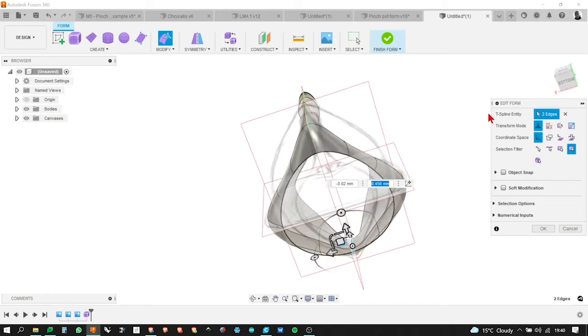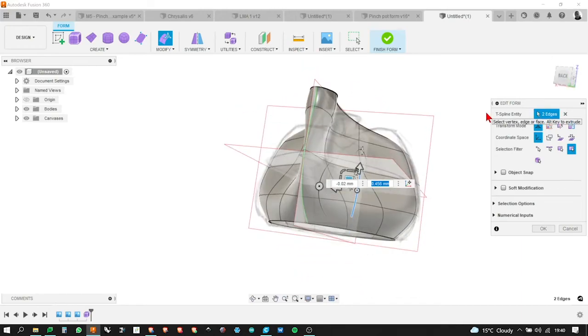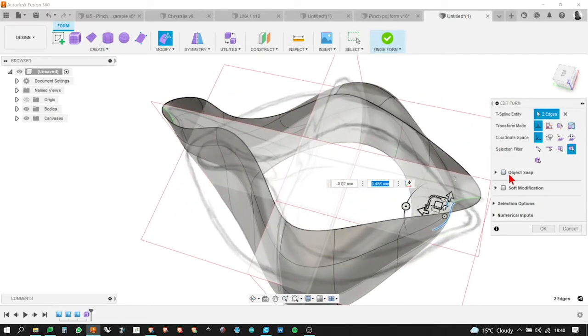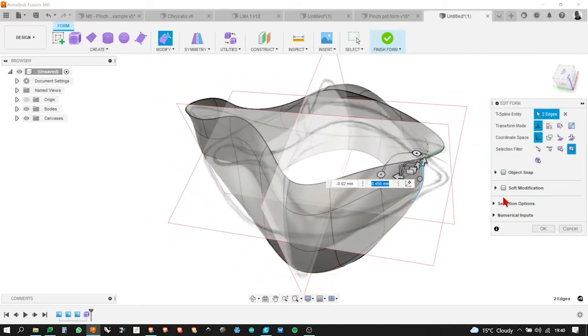And you can just work your way around and have a look until you're happy with the shape. And as I say, you can go on a very long time in this, getting it just how you want. And do remember, if you go a few steps down the line and you've got to the point where you liked it, sort of 4 or 5 modifiers back, you just Control Z to go back to an earlier stage in your modifier. That makes sense?